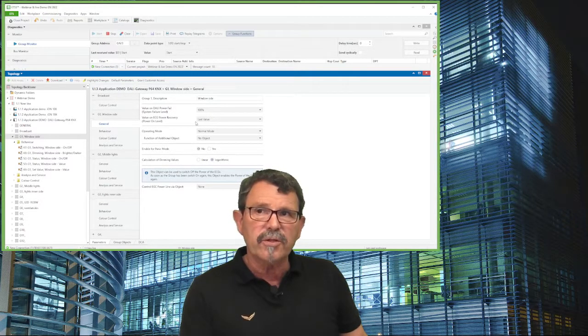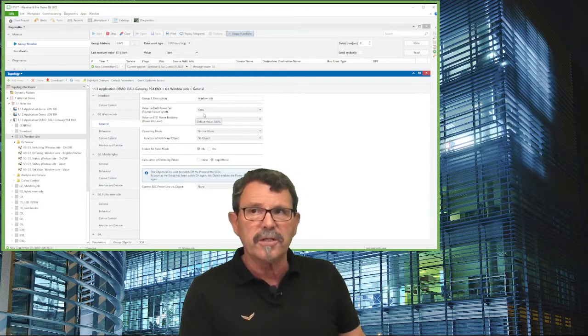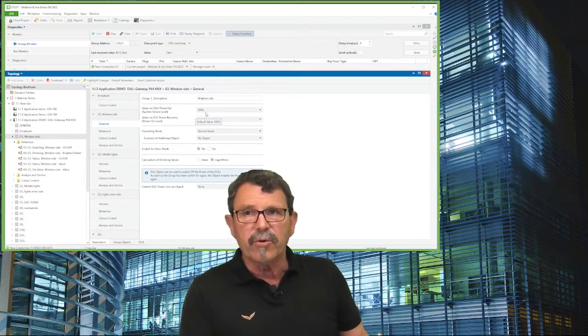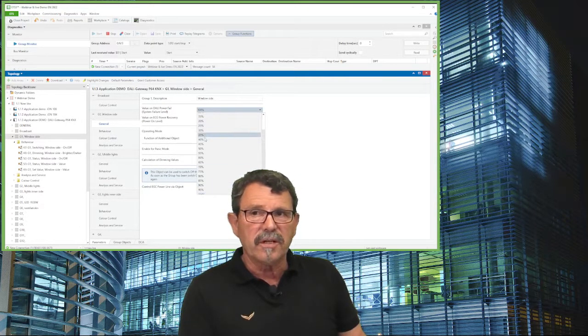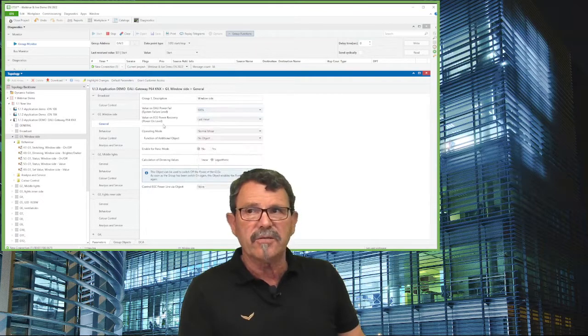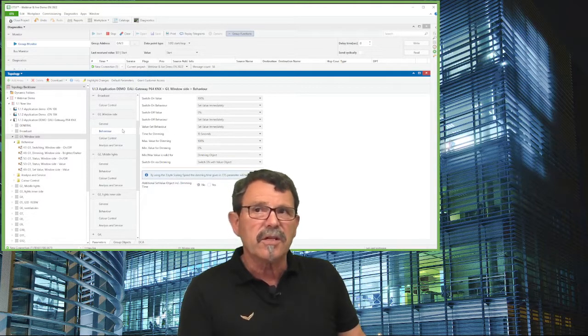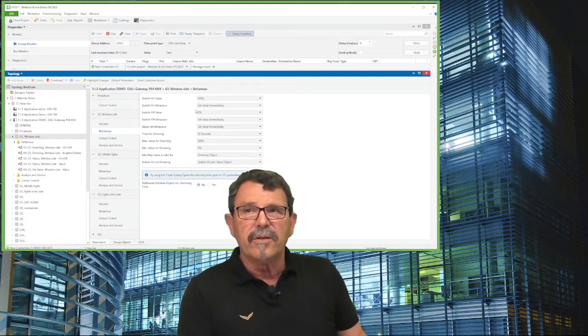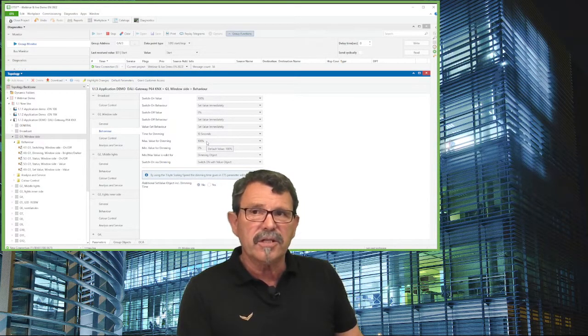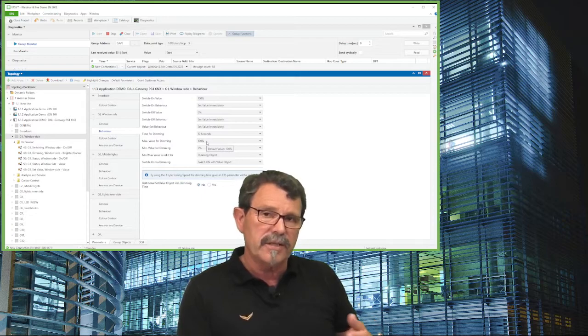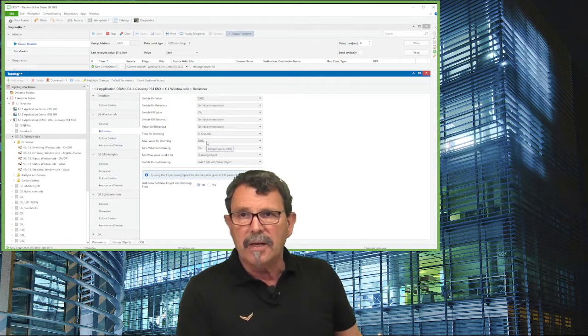here we can adjust, for instance, what we intend to do, what is the brightness in terms of power failure from the DALI side, for instance. However, I think this is stuff which you know. The different settings here, you can adjust, for instance, the level, minimum brightness, maximum brightness. This is good to know, finally.